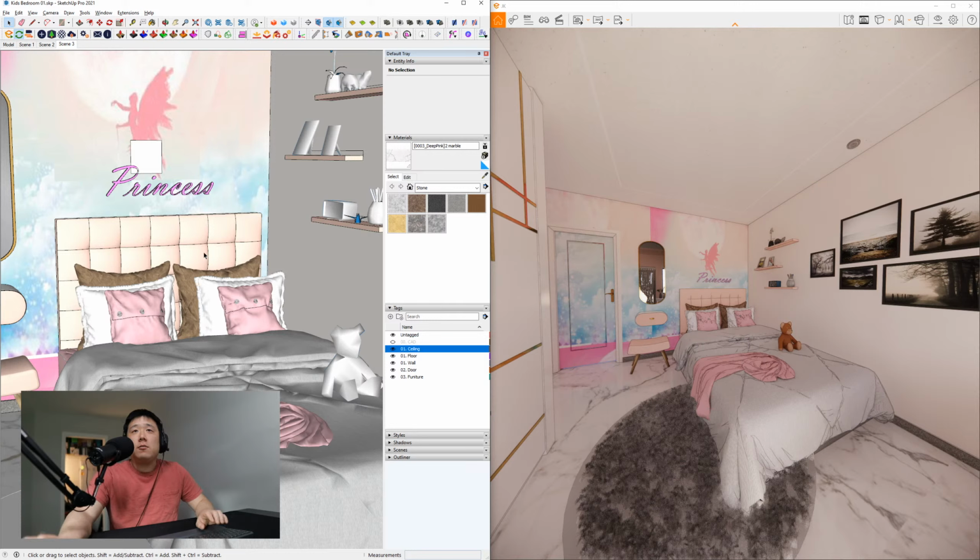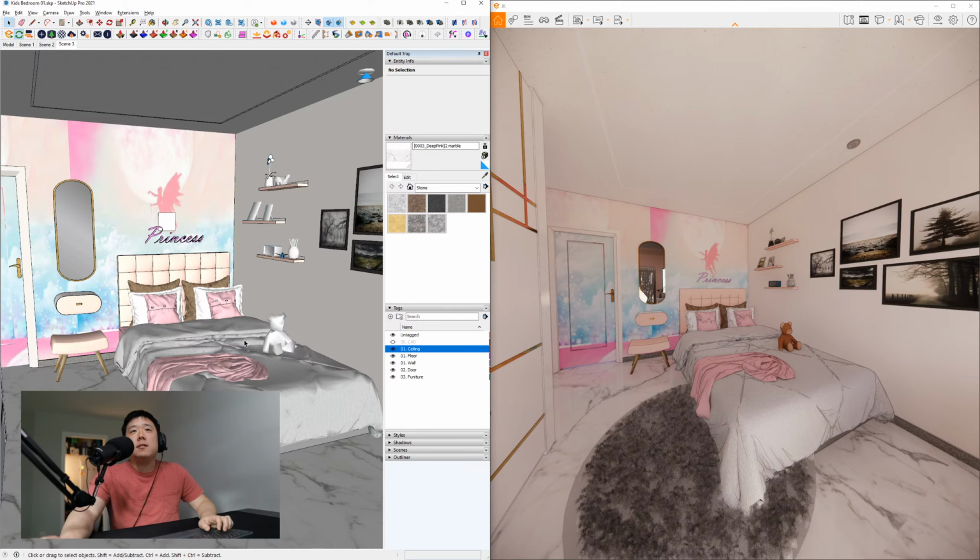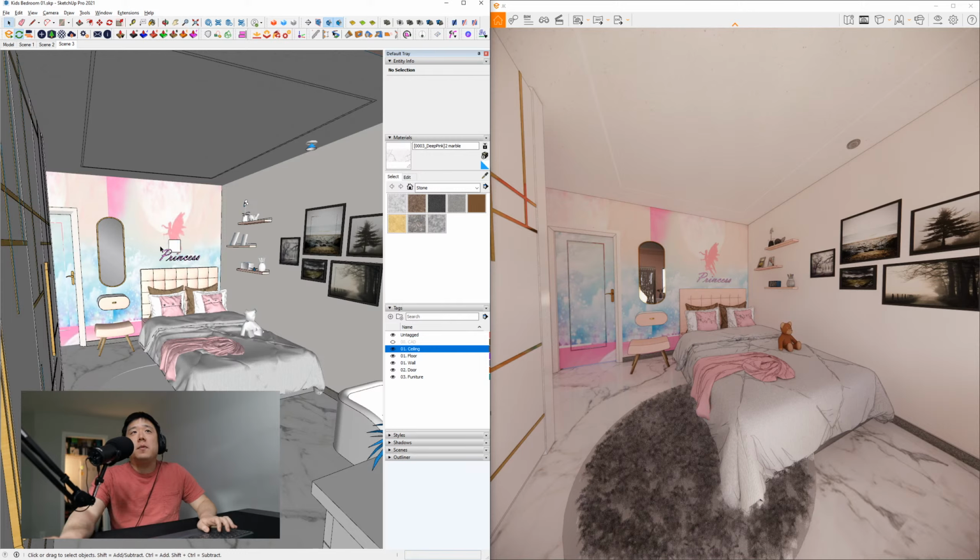So in order to widen your view, apparently Jayant already has done this, but if you hit Z once, which is a zoom tool, you'll see on the bottom right corner of SketchUp, it would say 35 degree, which is a default. And then you can type in 60 DEG, enter. And then basically that will give you sort of the widened view. 60 degree is usually okay in terms of tight space. If you want to increase it more, you can do 80 degree.